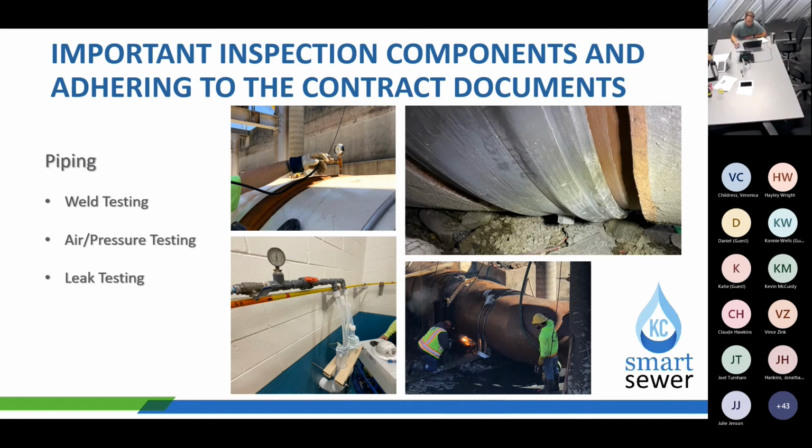There's static air and pressure testing, pneumatic testing, static water pressure testing, just pressure testing of the pipes. A lot of times it's just visual leak testing of some of the stuff that's done there as well. So there's a lot of different types. Working with the contractor to understand when these elements of the project are going to take place is pretty important.